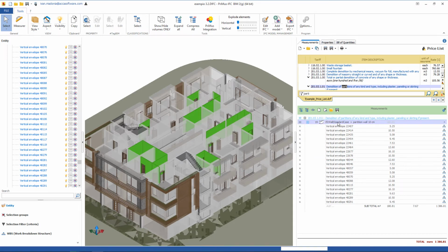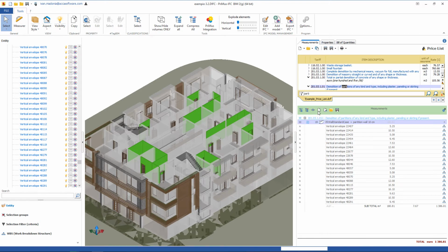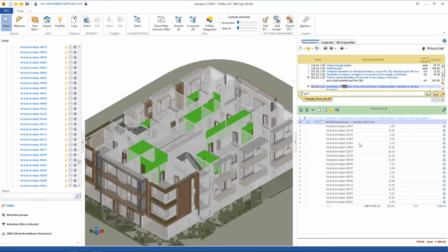The measurement rules, entity plus processing plus measurements, created in a project can be reused in other projects thanks to the possibility of saving them as a model or as template, set on multiple models in special archives. The loading of models and or cost estimates BOQ templates into a new project determines the quantity takeoff of one or more entities of the model in the IFC format. Matching between entities and cost estimates BOQs models takes place dynamically only if the entities on the new project meet the conditions of the measurement rules of the chosen model template.